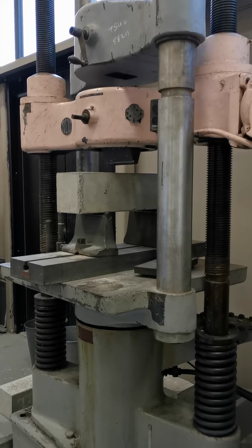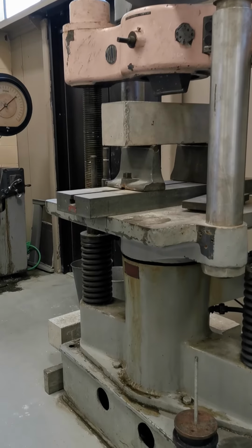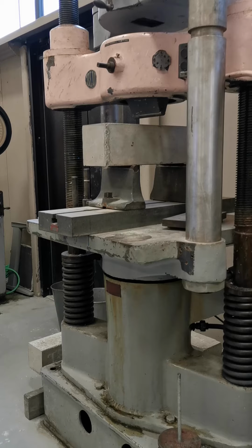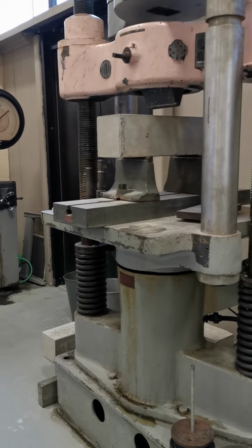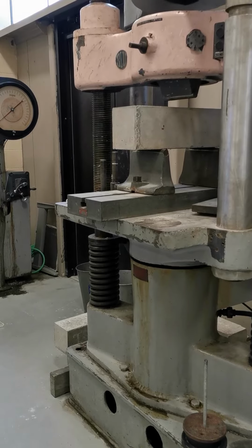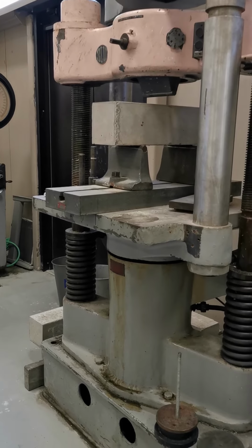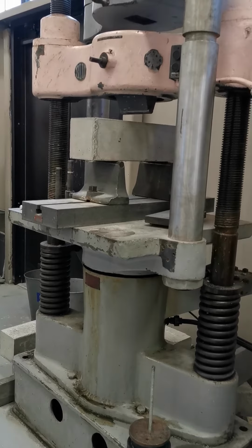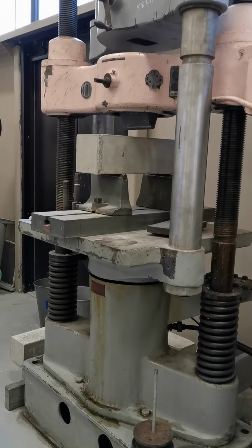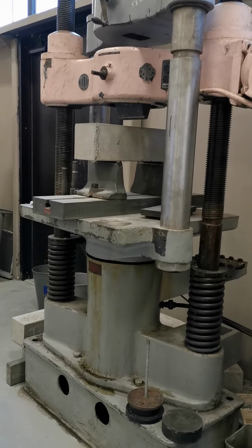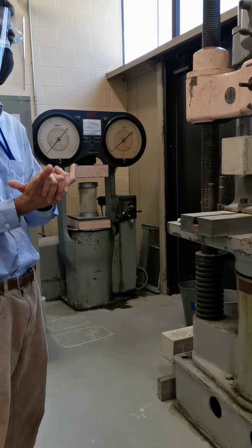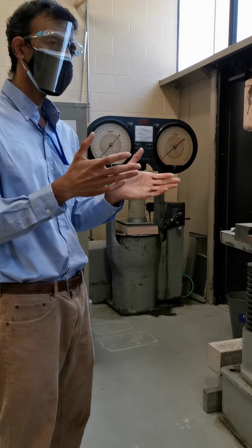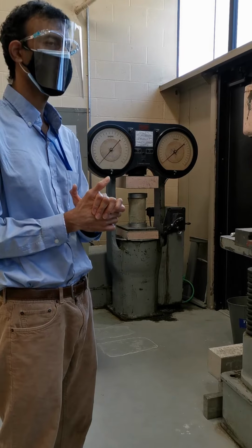So then for both experiment 1 and experiment 2, the students perform finite element simulation using Abaqus, for which we have 20 student licenses. For the simulation of the concrete compression test, the students primarily try to observe the effect of friction between the surface of the cylinder and the loading plate and how it affects the failure pattern observed.